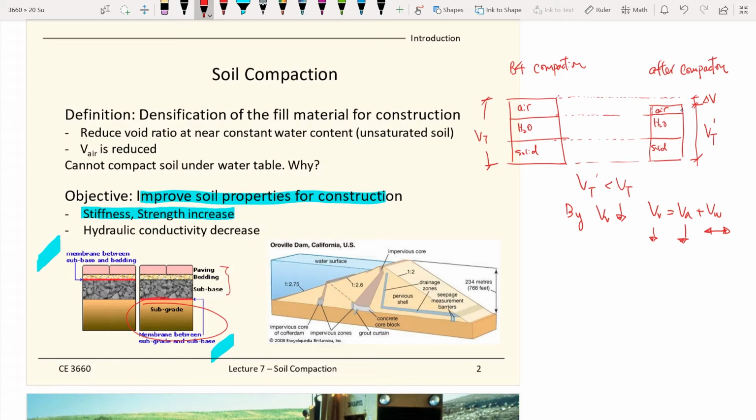You want to control the density of your subgrade soil, your very last grade of soil, such that the soil is strong enough to support all the loading above it, including the loading from the pavement and also the expected loading from the surcharge.